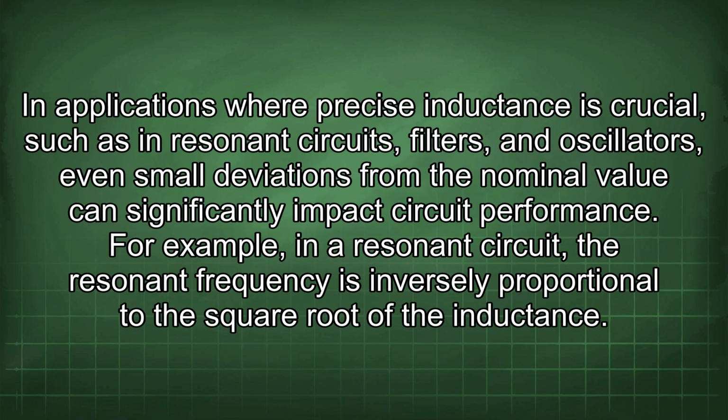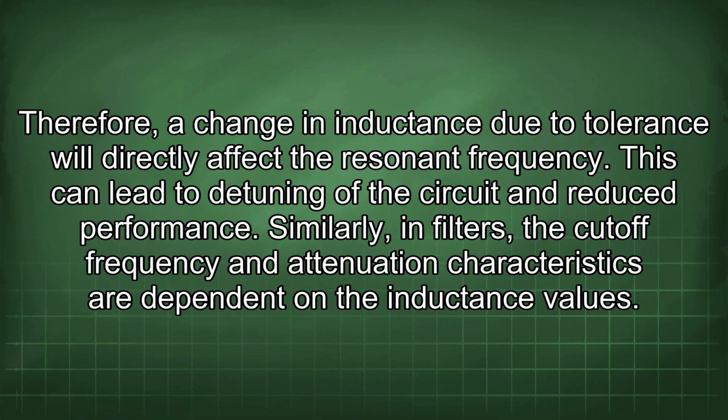In applications where precise inductance is crucial, such as in resonant circuits, filters, and oscillators, even small deviations from the nominal value can significantly impact circuit performance. For example, in a resonant circuit, the resonant frequency is inversely proportional to the square root of the inductance. Therefore, a change in inductance due to tolerance will directly affect the resonant frequency. This can lead to detuning of the circuit and reduce performance.